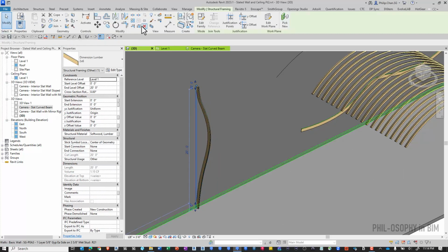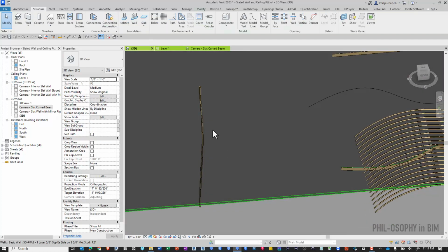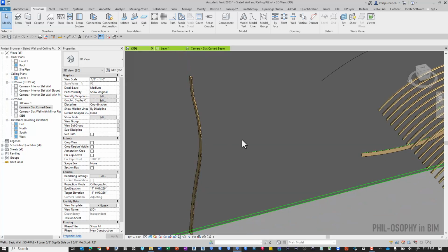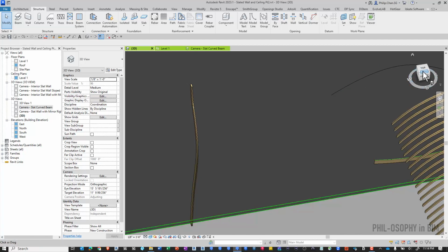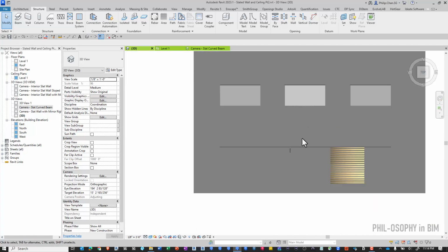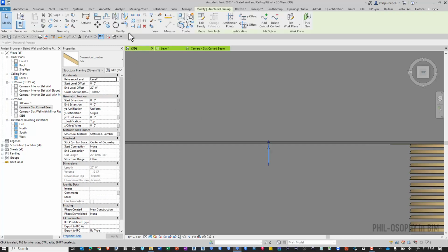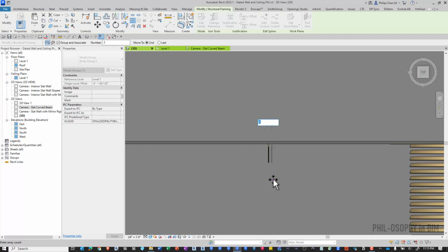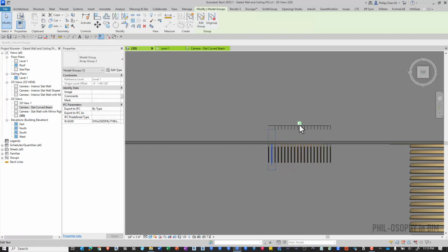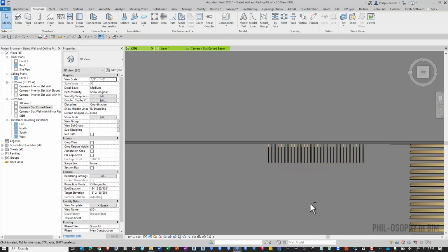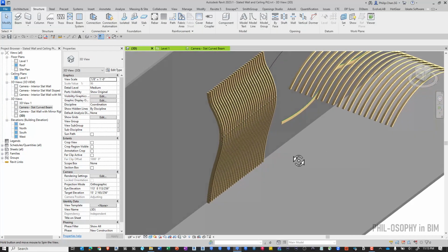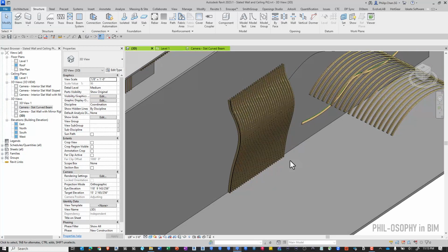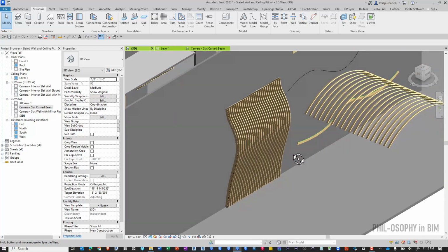Let's get rid of this one. If I have a wall or slat in a vertical application, I can again use the same concept of array. Let's go to the top view and take this beam here and use array. Let's do 6 inches on center this time, and I want 20 of them, maybe more, and just create this wavy wall system. Very simple and very effective.